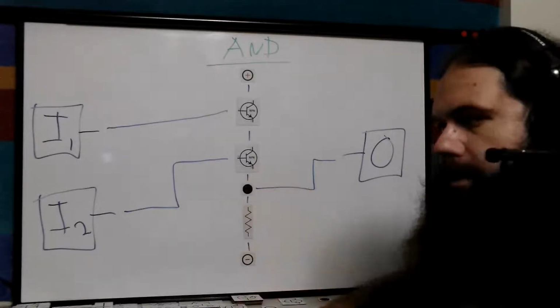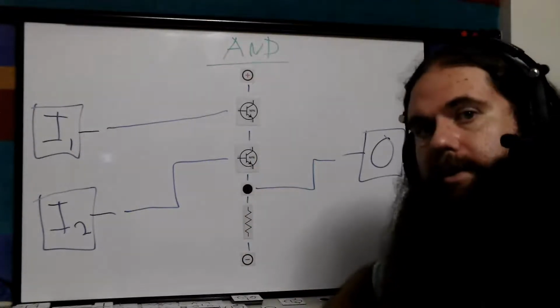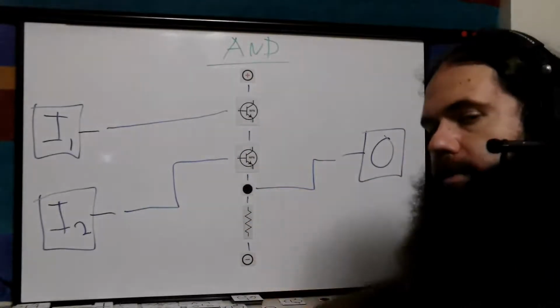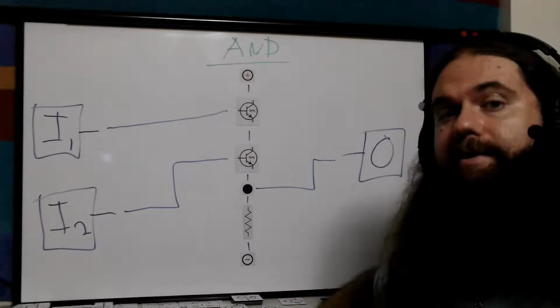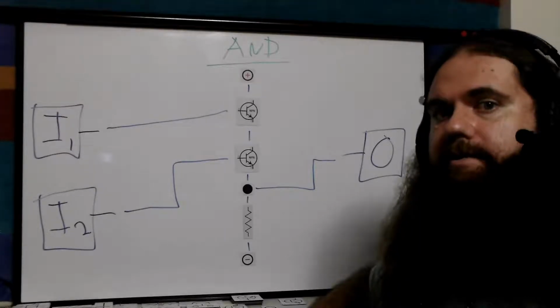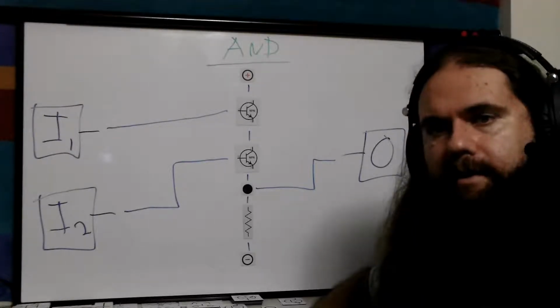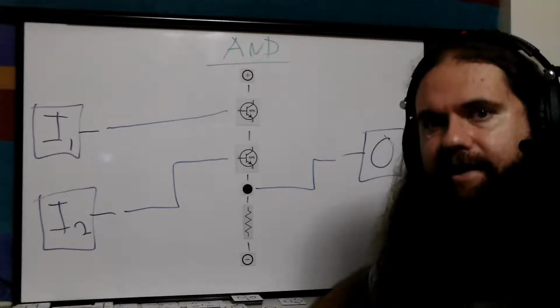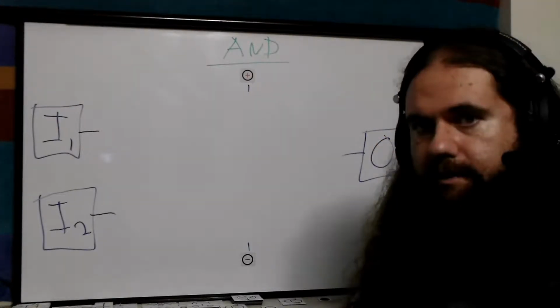If you use a MOSFET here, that won't happen, and this will work just fine because this will be 2 switches. So you can't do this. But remember how we said NAND gates can make any gate, including AND. So we don't need an AND gate. We can use a NAND gate. Let's do it. The best part is we just flip it around.